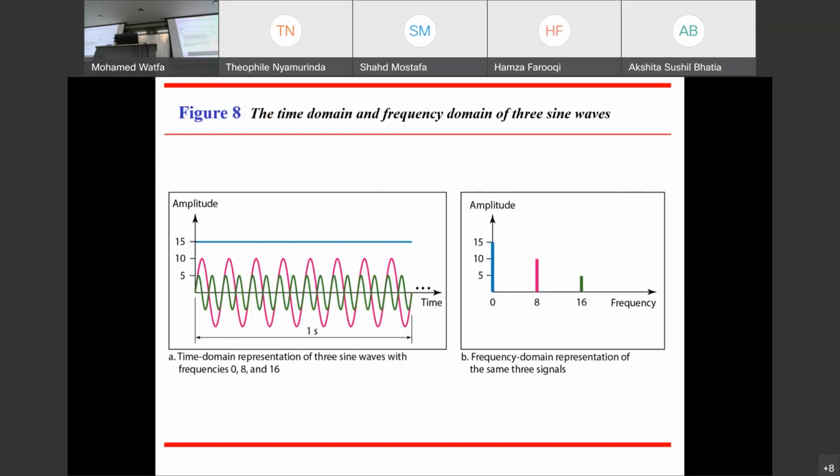As I just mentioned, the frequency domain is more compact and allows us to deal with composite signals. Again, very similar to what I was talking about. As you can see here, it's very complicated, right? Humans can't deal with this, especially if I have 20 of them on top of each other. But because they're all periodic, it's easy, like with magic, I get this. So what is this telling me? How many signals do I have? 3. Again, 3 different amplitudes, 50, 10, 5, and 3 different frequencies, 0, 8, 6, based on what we have. You could do the calculation, and you see you get the same answer.